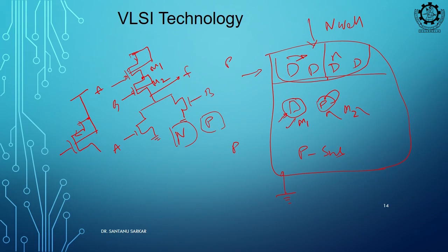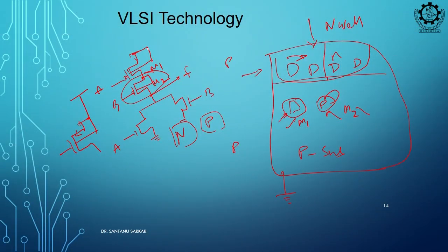So, in PMOS, although not suggested, by default all the bulk of PMOS should be VDD, and in NMOS all the bulk should be ground. It is a rule and you should follow this, but for PMOS, for this kind of structure, instead of VDD you can also short it with the source. That is okay, but you should not do this, but it is okay.